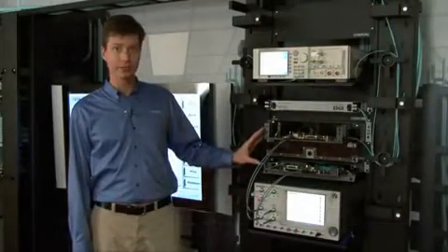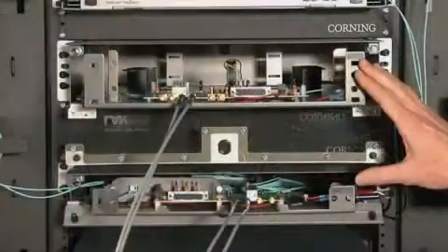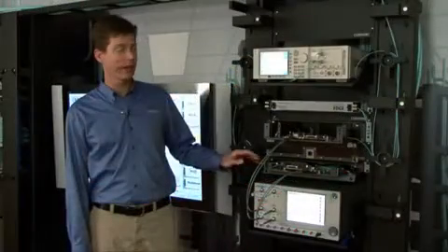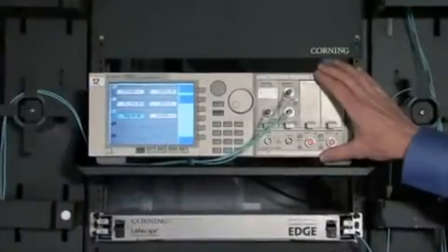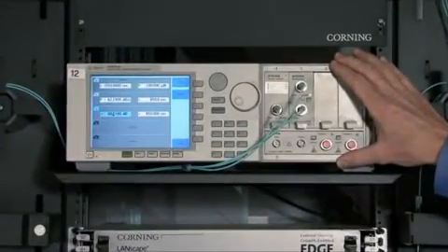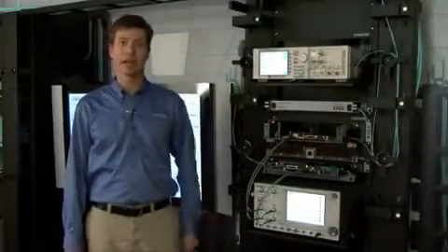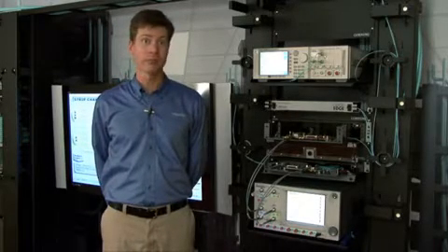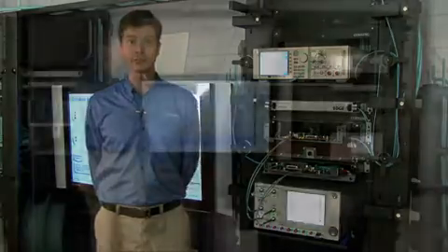We also have transceivers on these evaluation boards at 850 nanometers, one for transmit, one for receive. And the last component is an optical attenuator used to simulate system impairments. These components let us analyze different fiber designs, hardware designs, cable, and the interaction with different transceivers.